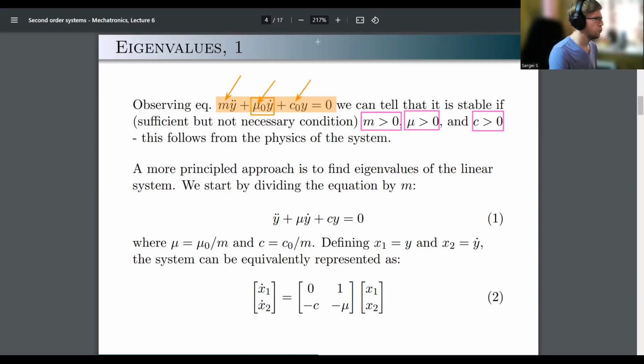You can write down a Lyapunov function for it and prove stability through the Lyapunov function. It wouldn't be too difficult. You can also just count eigenvalues of the system. You'll find that they will be negative. Okay. Now, it is important to keep this test in mind because for second-order systems, it is extremely useful.